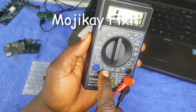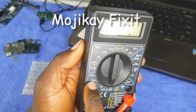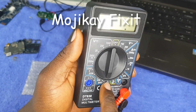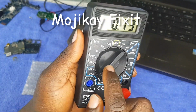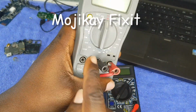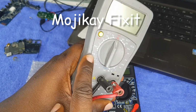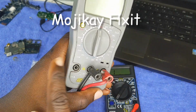This is 200 ohms, 2000 ohms. This is 20,000 ohms, 200,000 ohms. You understand? That's 200k ohms. This is 2000k ohms. So it goes from the smaller to the highest. Okay, so you read your resistor from this, and also from this multimeter as well. The same thing applies. You see all this 200 here, k, 20k, 200k, 200 mega, 20 mega ohm. Okay, this mega ohm, I told you we have ohm, kilo ohm, and mega ohm earlier, if you remember.